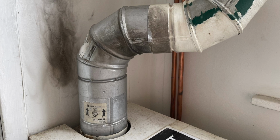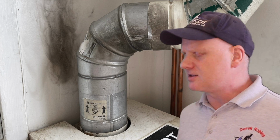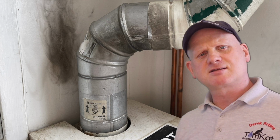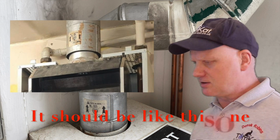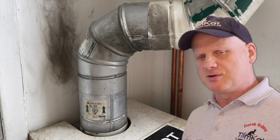Now let's finish off with this picture and let's see exactly how many faults you can find with this open flued boiler, if there are any faults, that is. So I'll give you a few seconds to have a look and see what you can come up with. Now, how many faults have you spotted behind me here then? Shall we start at the bottom here, above the draught diverter? Can you see that the actual appliance adapter isn't sealed to the draught diverter? So that's the first one.